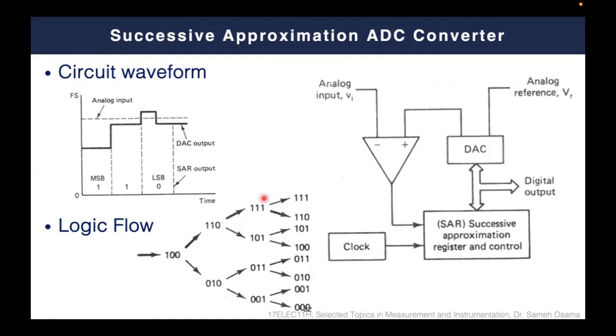Still, it's a bit slower, of course, when we compare it with the single slope ADC, which we can say is the simplest, fastest ADC, with the source of error we already considered. But again, it's a very efficient way, and that's why this is one of the most famous ADCs used nowadays, which is the SAR logic-based ADCs.